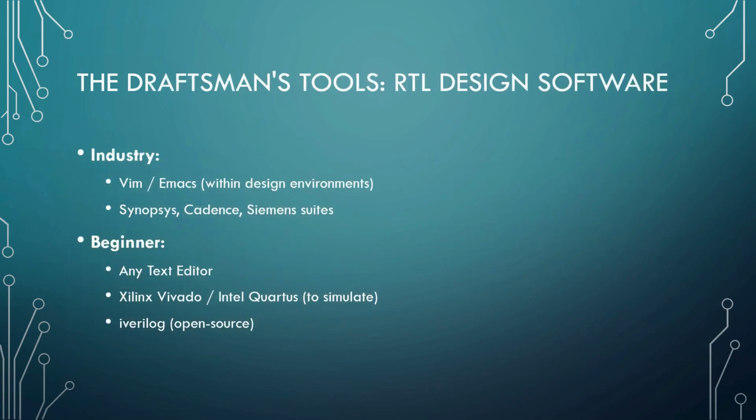The industry uses advanced text editors like Vim and Emacs, often integrated into massive design suites from Synopsys, Cadence, and Siemens. For beginners, any text editor works, and you can test your code using the free simulators from Xilinx and Intel, or open source ones like iVerilog.